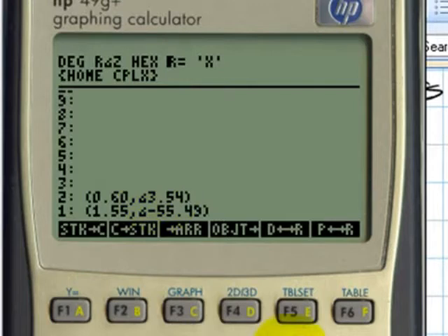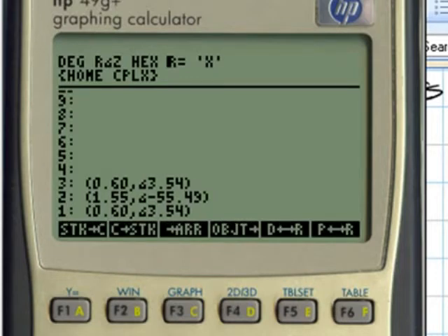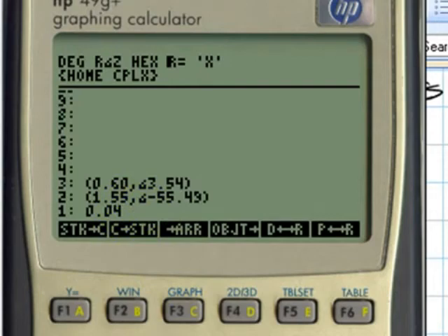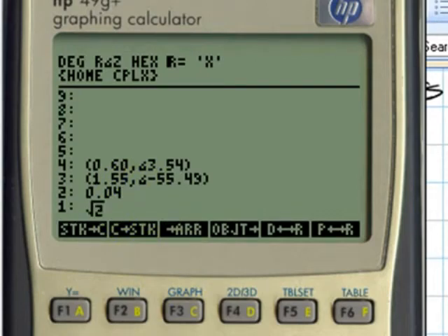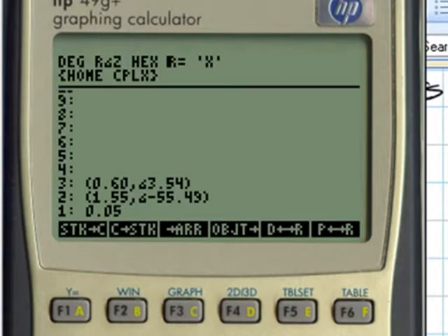That current, this one, pick, enter, and now we are in polar. Let me take it from the complex number format to the stack. I want the sine of that. It's in degrees, yes, that's right. The sine, multiply times 0.6 root 2, multiply, evaluate that as a number, and that is the value of the initial current in the inductor.